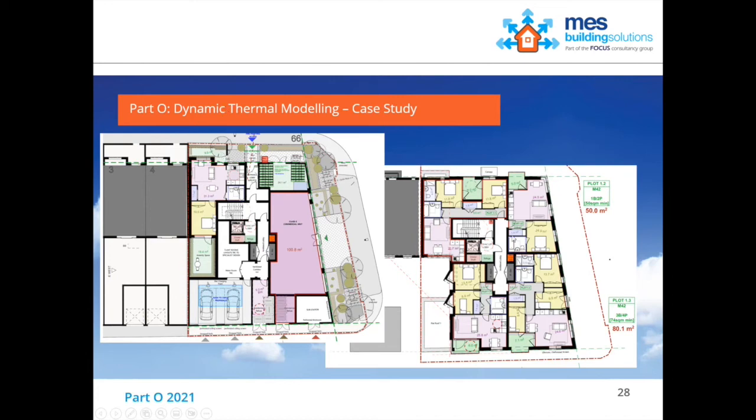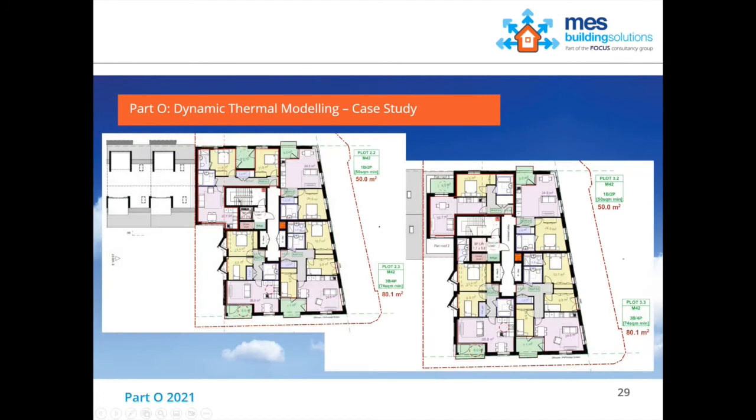And in fact, as we go up, you'll see all the ones in this core of the building are able to be cross ventilated because we've got opening windows here, and also opening windows on this facade over there. North is the top of the drawings on here. That's north, south is down here. As we go up the building, you've essentially got 4 flats a floor, one there, one there, one there, and then this one over here.